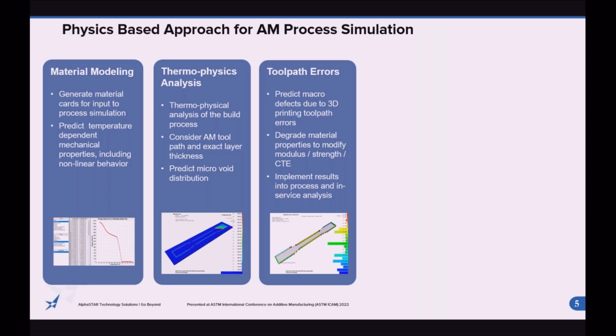Next, we consider not just toolpath or macro effects, but the implementation of the G code, because that's ultimately the driver of process parameters. And so while you may have a sense of what process parameter A or B might do at a particular moment, when you compound that over time, you get a sense of the generation of defects and potentially the effect of those defects on as-built material properties and ultimately on the fabrication of the part itself.